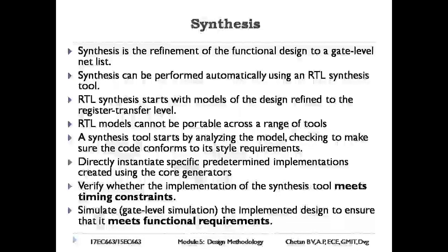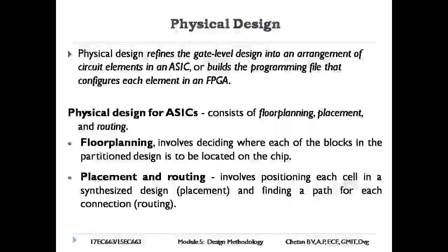Directly instantiate specific predetermined implementations created using the core generators. Verify whether the implementation of the synthesis tool meets timing constraints. Simulate the implemented design to ensure that it meets functional requirements.